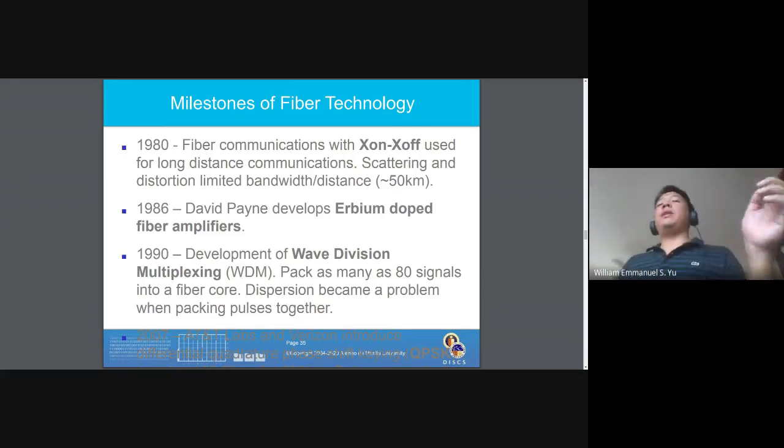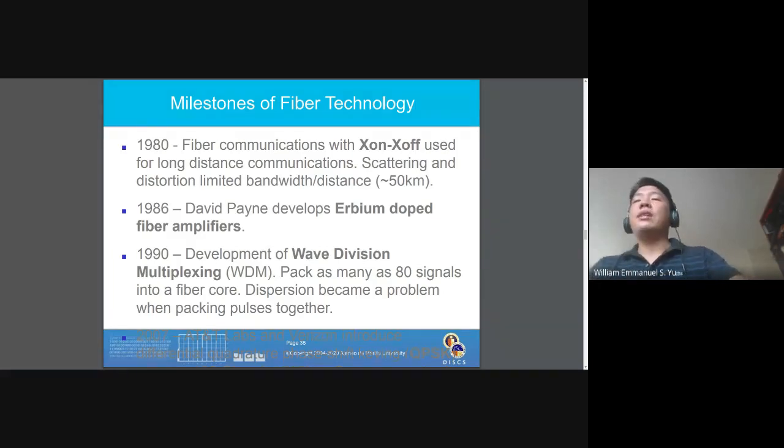The problem with this optical-electrical conversion is it is not the most efficient conversion because then you get bogged down by the speed of the electrical component, which is not as fast as optical, right? That's why these erbium-doped fiber amplifiers are nice, because you don't have to have an electrical signal. This also means that the repeaters can be floating in the middle of the Pacific Ocean without being powered.